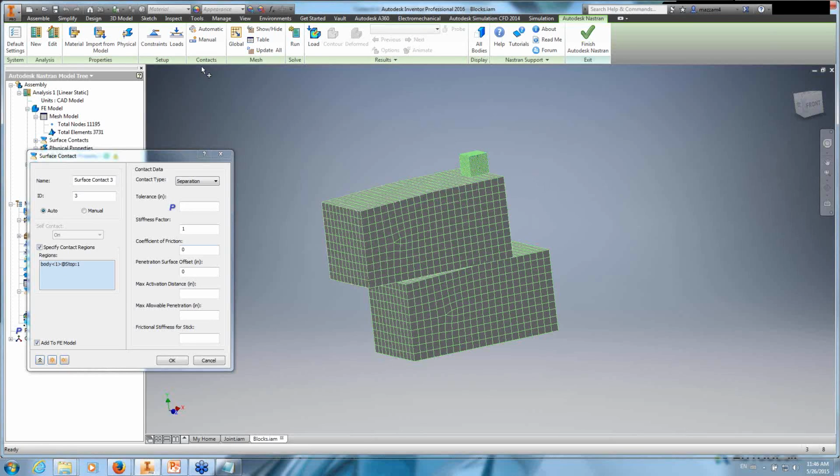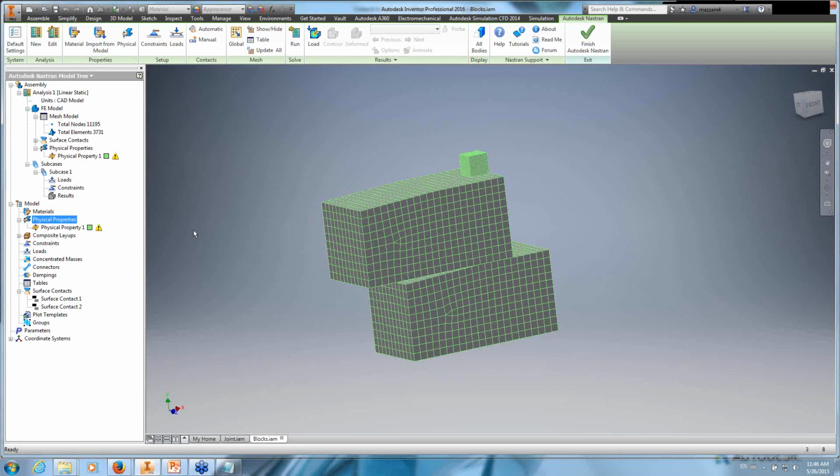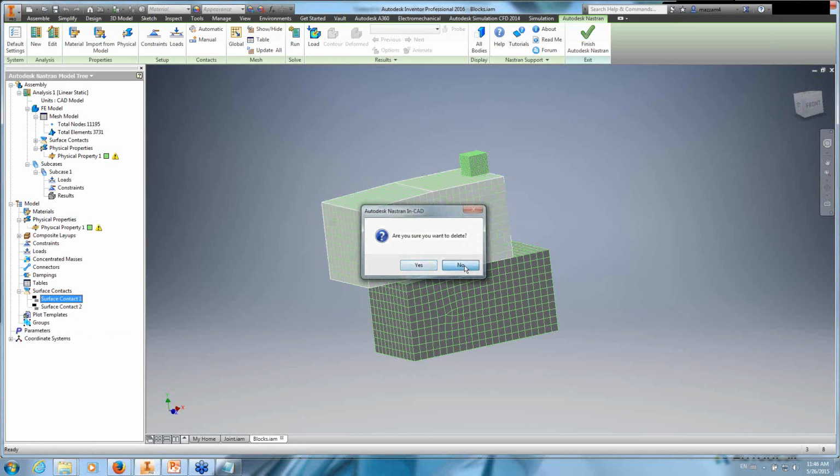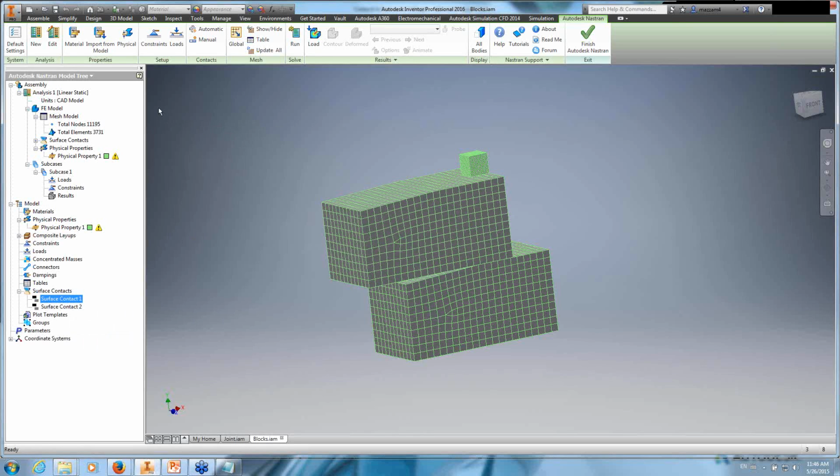All right, looks like we got another question here from Daniel. If I flush and mate parts in an assembly, do I need to define surface contact for every part? I don't know if you want to tackle that one, Marwan. No, that's what Al showed, that you would make the default a certain contact. So I don't need those.